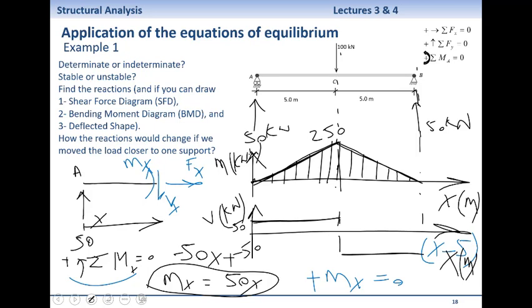Okay. We normally use the letter small w, small q for distributed load. So let's say W. W is 0. There is no distributed load, yes? W is 0. Look at the bottom diagram, which is the shear force. How does it look like? Constant, yes, for the first half, and then again constant for the second half. You see that?